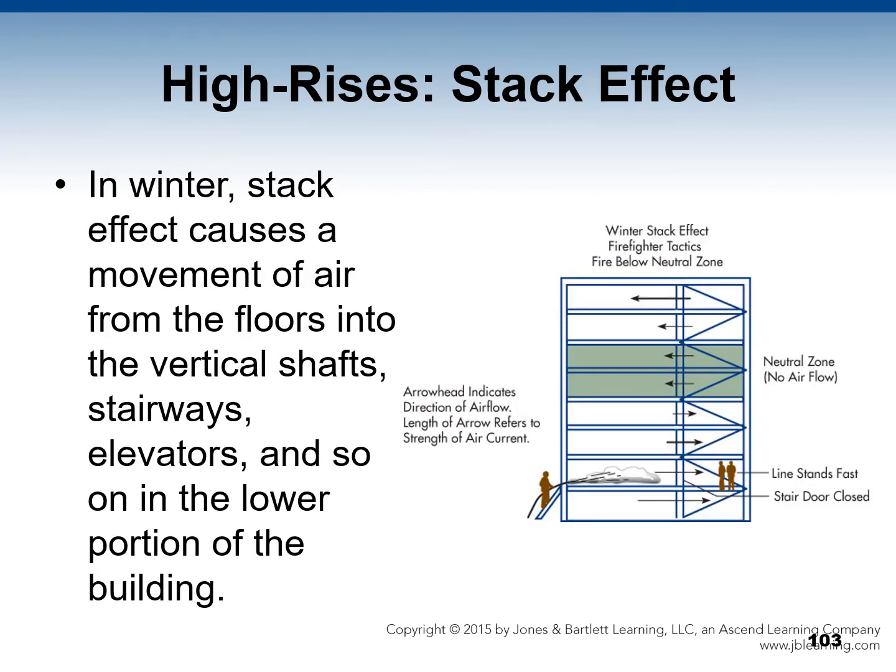Under winter conditions, the stack effect causes a movement of air from the floors into the vertical shafts, stairways, elevators, and so on into the lower portion of the buildings. If floors were completely cut off from one another, there would be no overall stack effect because there would be no connection between the floors.